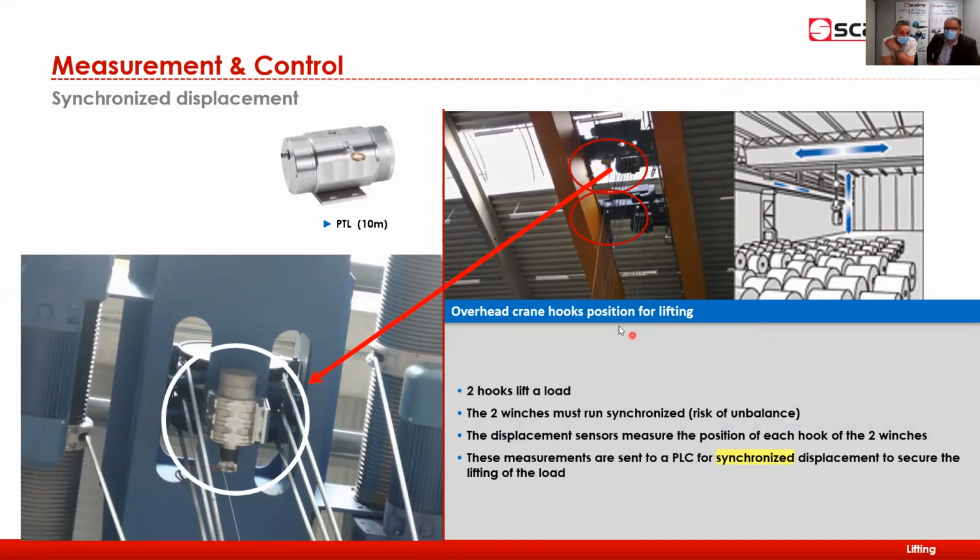So with this information, for each system there is a sensor cable, displacement, and with this information the PLC can synchronize the displacement, the filling. Okay, so it will equalize the way it lifts on both sides so that it remains flat. Exactly, horizontal. Okay, interesting.